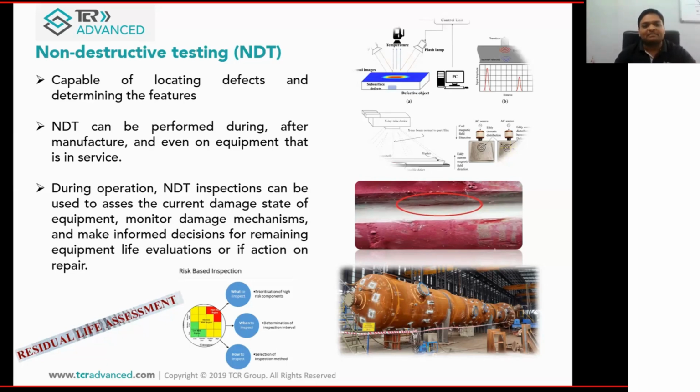In the manufacturing stage, after manufacturing, we can use different NDTs by checking the shell seam, long seam, and nozzle joints of the pressure vessels. And in in-service inspection, you all know that for plant components, we are checking thickness measurement, flaw detection in shell seam and long seam joints, and all other inspection, visual inspection, thickness measurement, then internal oxide scale in boiler tube analysis.